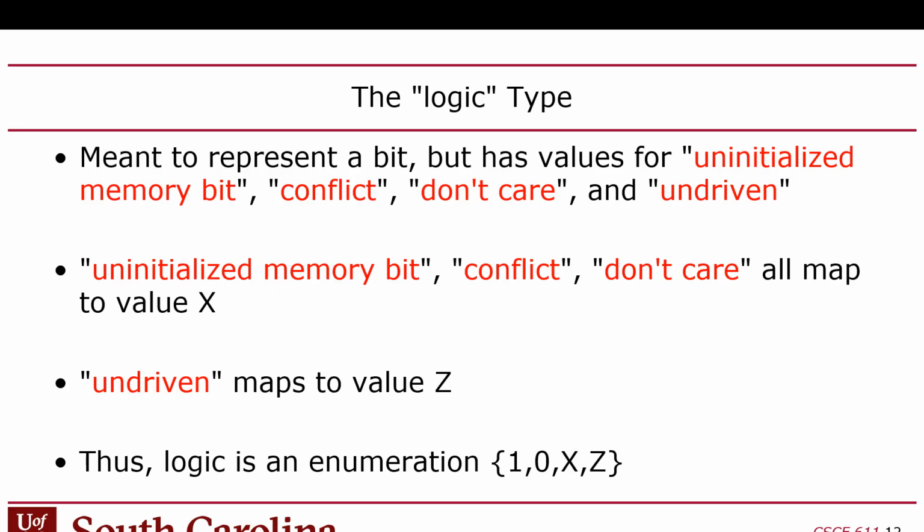So to summarize, Verilog has what's called four-state logic. It has 0 or 1, and then it has X or Z. The problem is that X means three different things. It can mean don't care, don't know, or conflict, which is something I don't like about Verilog. In VHDL, they fixed this problem. In VHDL, a don't care is a dash, a hyphen.